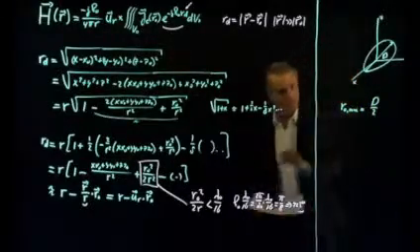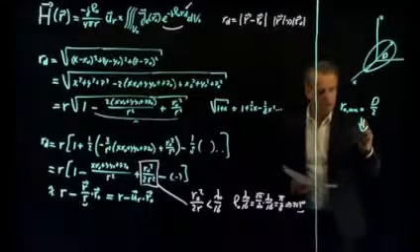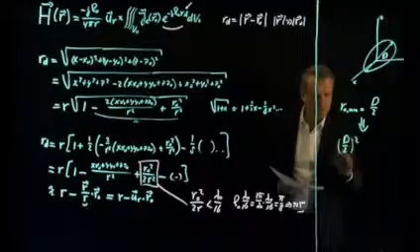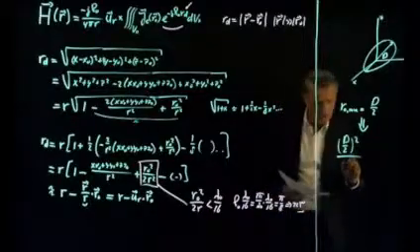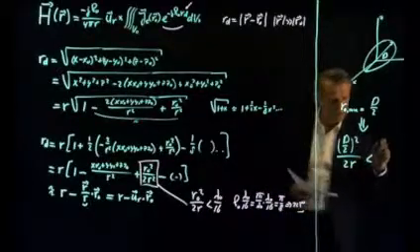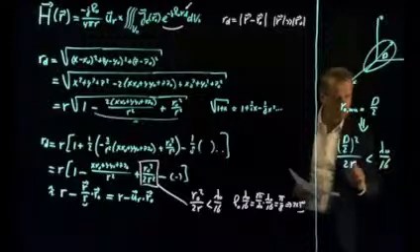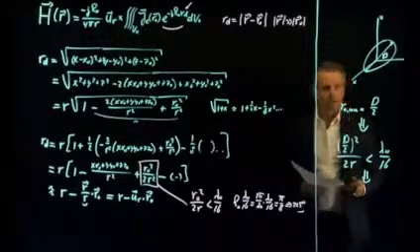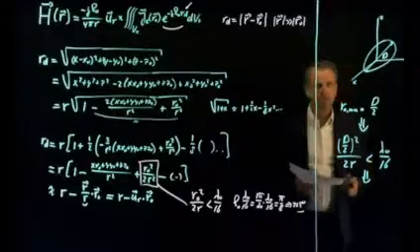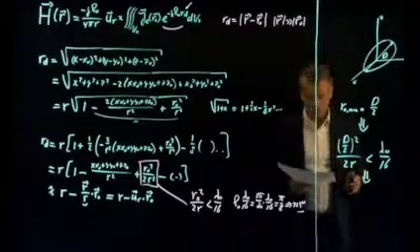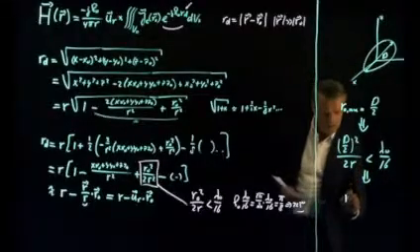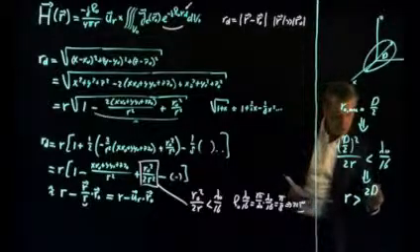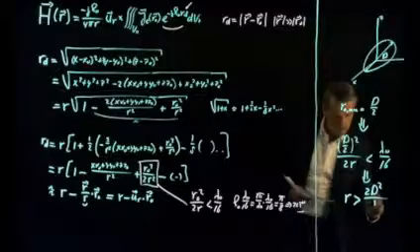And if we apply this criterion, then it means that (d/2)² divided by 2r should be smaller than λ₀/16. And that brings us to the well-known far field criterion, which we already introduced in one of the previous web lectures as well, that r needs to be larger than 2d² over λ₀.